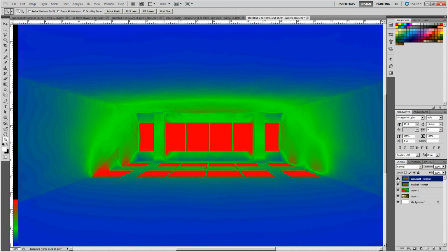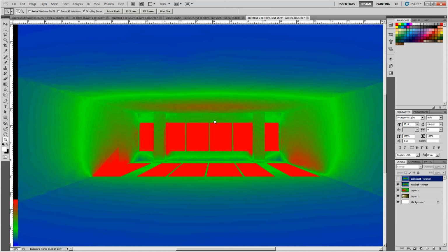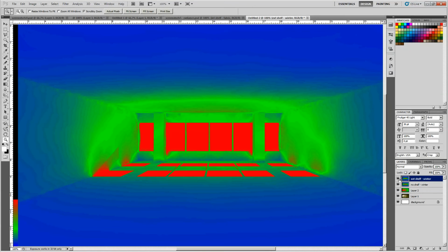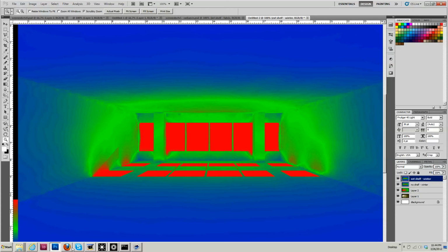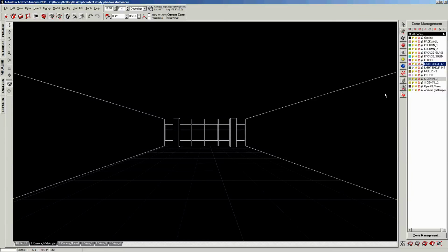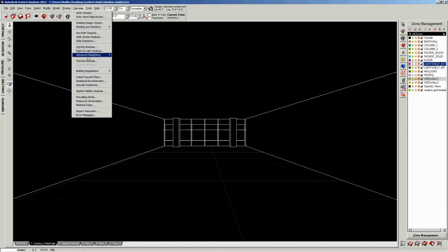And if you think about the ceiling, how does the ceiling get lit here? It's actually an indirect reflection of the sunlight that's on the floor, and there's a lot less in the center area, so that's why it's actually darker here. Darker doesn't necessarily mean worse, because this excessive amount of light also creates glare issues in this area. But let's finish this exercise, this experiment, by turning the exterior light shelf off and the interior light shelf on, and doing this one more time.